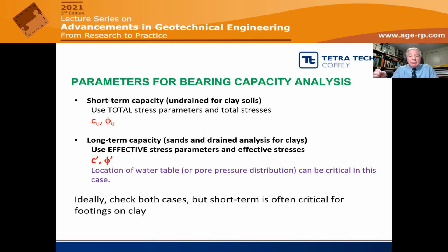In the long term, that will reduce the effective stresses in the clay and reduce the strength. And so if you're doing such a problem with excavations, you must look both at short-term capacity and at long-term capacity. And it's possible that the long-term situation may be critical under those unloading or excavation conditions.